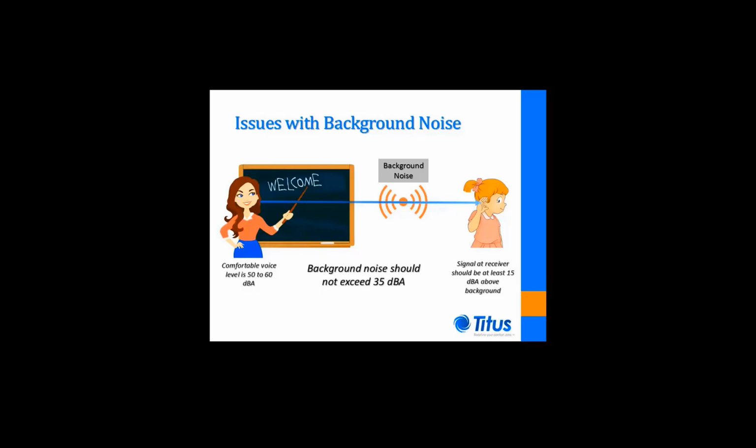In order for the teacher's message to be adequately heard and understood by the students, it should be at least 15 dBA above the background noise level. Therefore, the background noise level should not exceed 35 dBA.